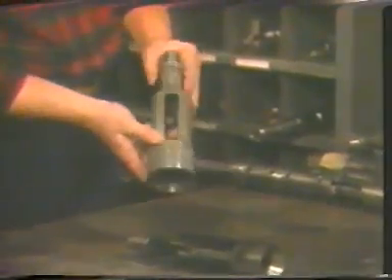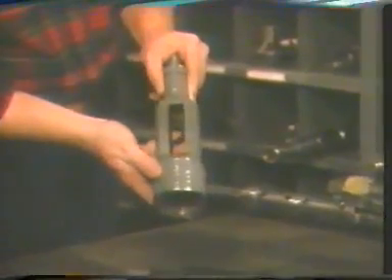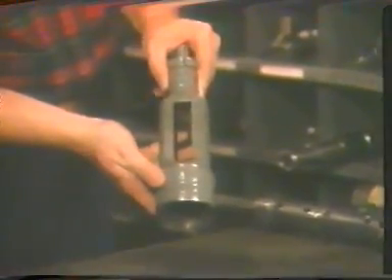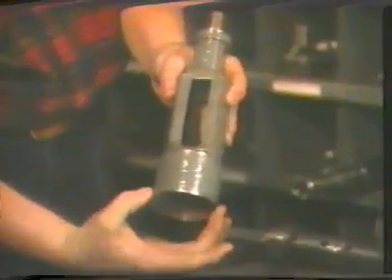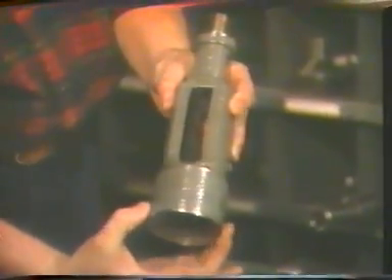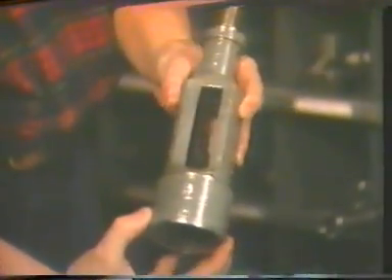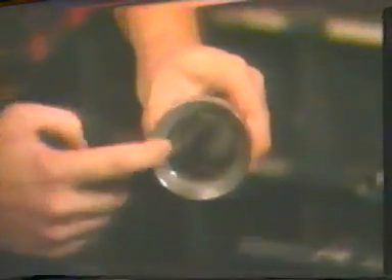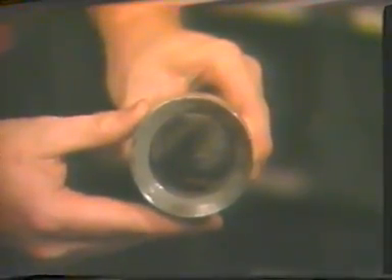This is the function of the tubing conditioning tools, which are normally part of the service equipment used by the wireline specialist. The tubing gauge cutter is normally run prior to any other wireline operation to check that the tubing is free of obstructions. These gauges are normally slightly smaller than the minimum ID of the tubing to allow the gauge to pass through the tubing but stop if any obstruction is encountered in the tubing bore. These gauges are beveled to remove paraffin deposits or light scale deposits from the tubing wall.